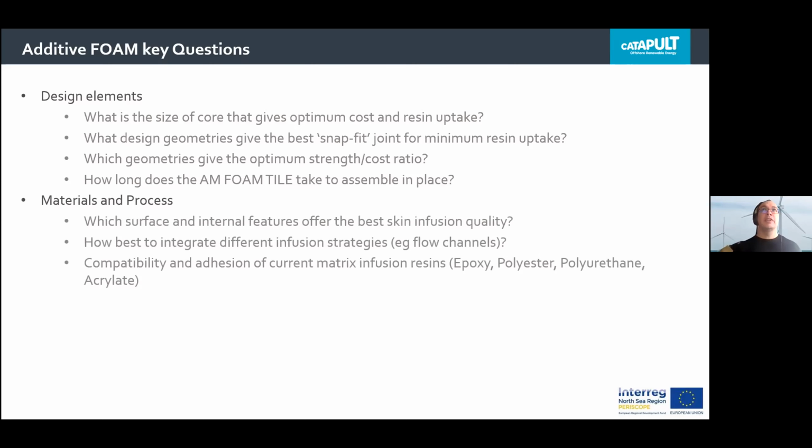Also, as to the materials and process, which surface and internal features offer the best skin infusion quality? And that goes hand in hand with the next one, which is how to best integrate those different infusion strategies, such as flow channels within the designs. And clearly, whatever material this tile is produced from, what's its compatibility against commonly used matrices used in blade manufacture, particularly epoxy, polyester, polyurethane, or acrylate?